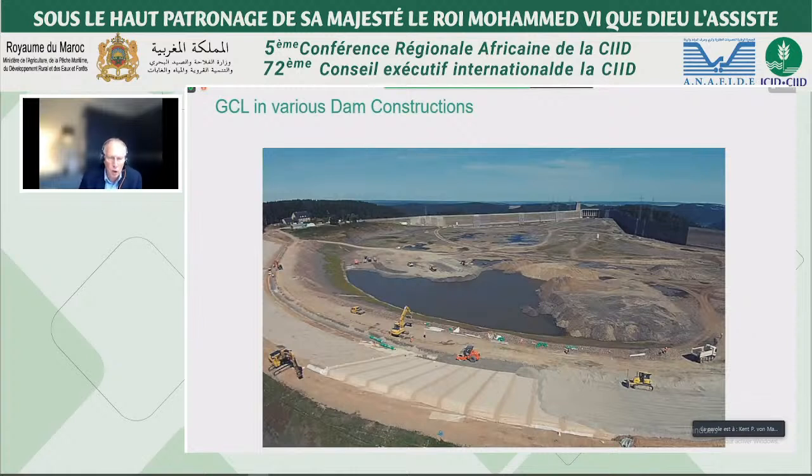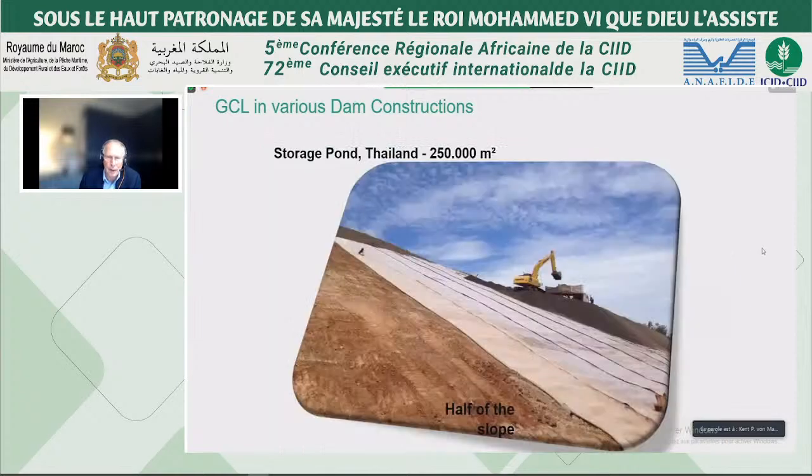In a hydro dam in Germany, there was a special product used. It was a GCL not with 5, 6, 7, or 8 kilograms of bentonite in between. It contained 12 kilograms of bentonite because it was a high security area, because on the downstream side, again, we had a lot of houses living in there, and the old compacted clay liner installed in this application just didn't work anymore. It did work for 20 years, but after that it started cracking, and this geosynthetic clay liner replaced the compacted clay liner, and it's successfully used since then.